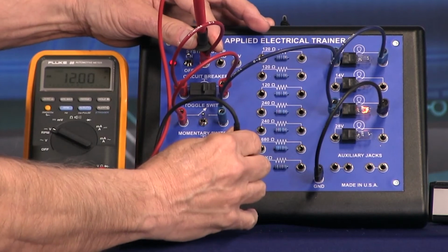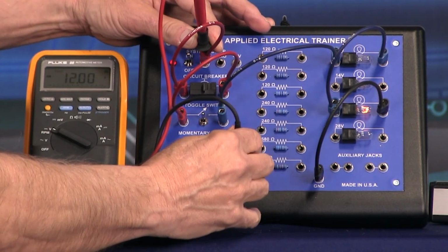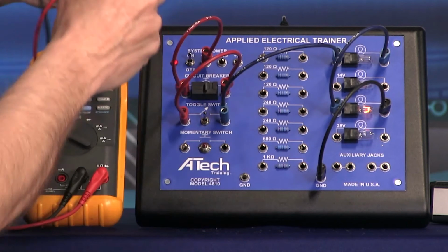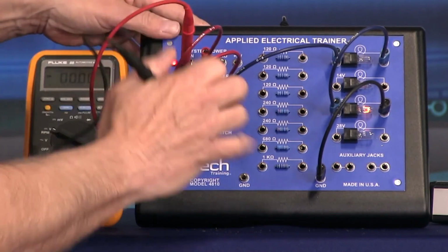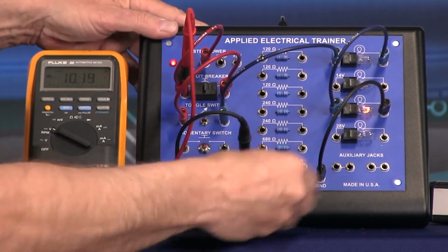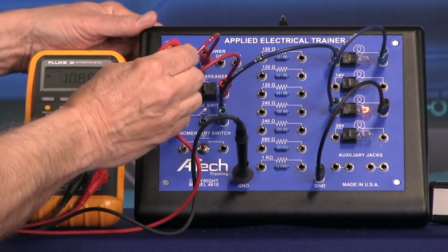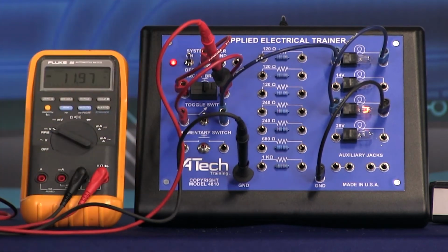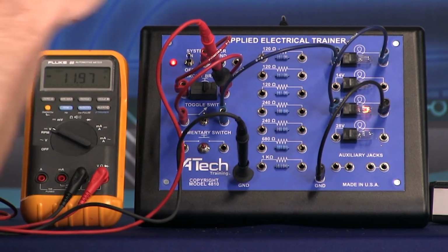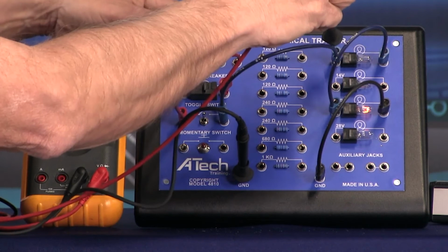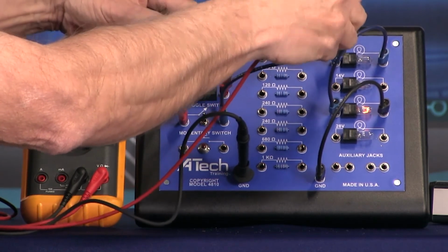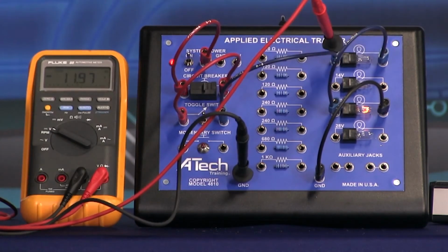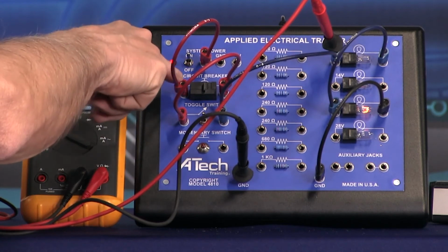Okay, I've got 12 volts going to the circuit, right? Notice that was a little different. And again, I'm going to go before this one. There's 12 volts before it, and notice I have 0.03 of a volt. Same process. Now, if I go before my load, I get 11.97, which I should have if everything's good. I know I had 0.03 here.